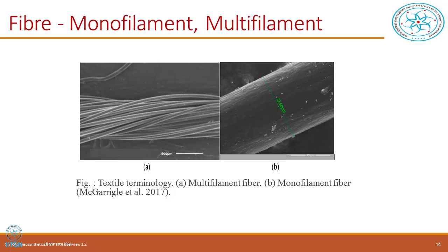And when you really look at a very highly magnified expansion of the material in an ultra microscope, this is the kind of cylinder which you are going to see, and here the filaments are twisted and put together. So what is that now? We had a continuous filament, and then after drawing and orienting, we try to twist it, and then round it up on a bobbin, and that is what we call a multi-filament fiber. So it is monofilament and it is multi-filament. Multi-filament fiber means actually it is a yarn now. So these words are textile words now.